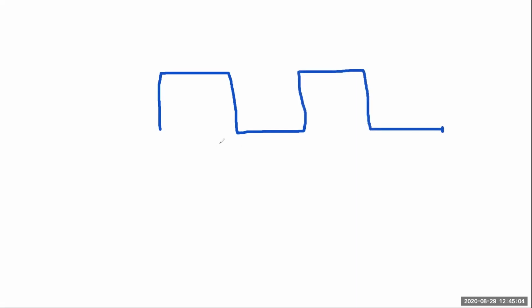We want to see these, but before that, let's see how many cycles we want to see. This is our high, this is low, right? This is 20 nanosecond, the total is 40 nanosecond, right? We want to see 2 cycles. So here you have 40, here you have 40. 2 cycle means 80 nanosecond. We want to see 80 nanosecond. If you want to see more, you can write more, no problem. So this is the transient analysis.